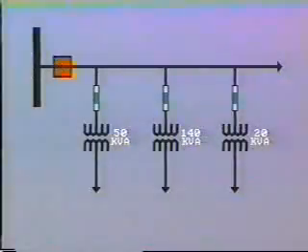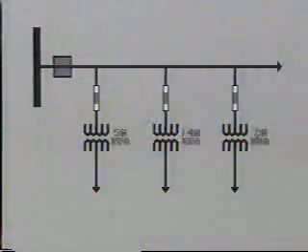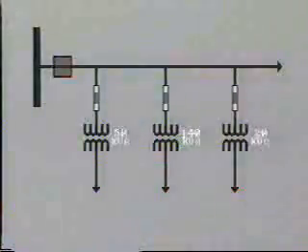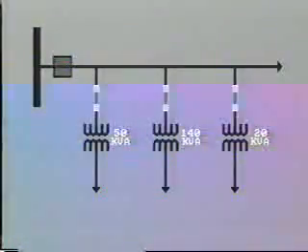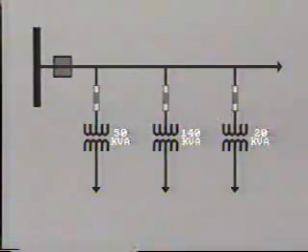On smaller transformers, it is usual to omit the primary side breaker for economic reasons. Typically, we may have many large and small distribution transformers tapping off a distribution feeder. The feeder will be fed from the substation bus through a breaker. But each distribution transformer will be protected by high voltage fuses only.